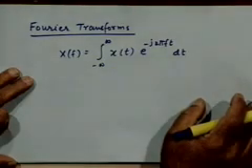Right? Where, what is a limiting procedure like? Do you remember? You start with a periodic signal with a finite period, and then you make the period infinity, right? And you get to the Fourier transform. And the important thing is the line spectrum of the original periodic signal now becomes a continuous spectrum, right? Continuous in the frequency domain.